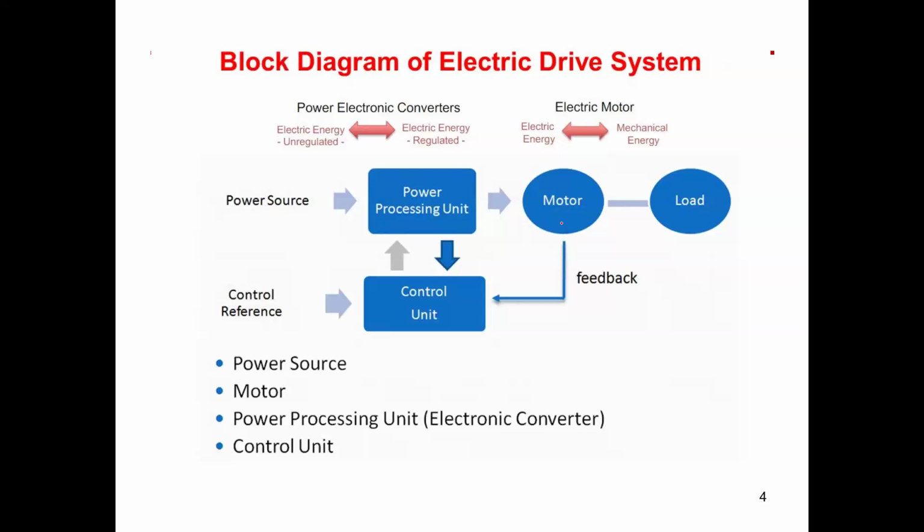Simply, we have what's called feedback, a sensor to measure the speed and control this speed to a certain command or reference value, and calculating the error. The error is nothing but the difference between the setting value, or the command, and the measured value we have from the real operating system.